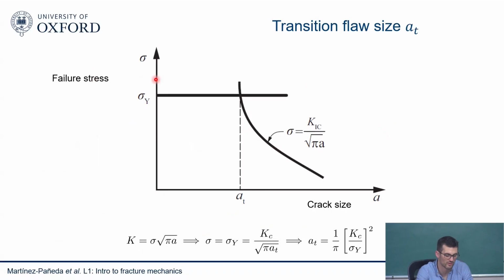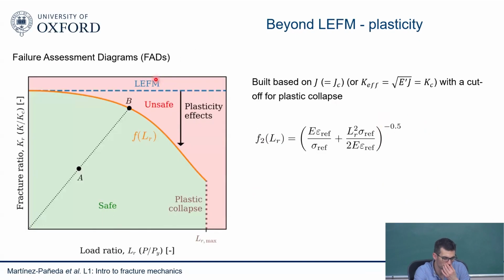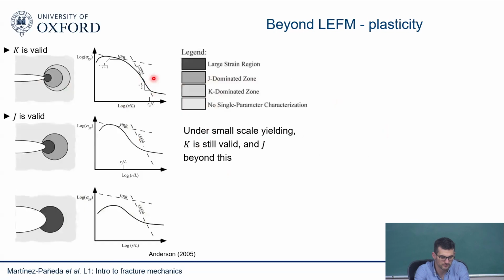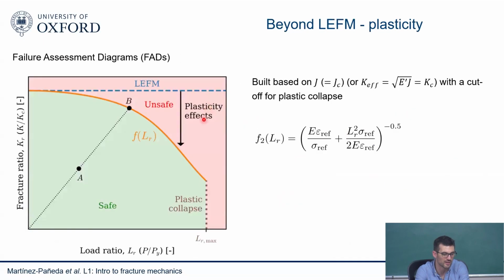This you can also use for elastoplastic fracture mechanics design. But they do something like this, where basically here I'm going to the extremes. I'm taking this stream, the plastic collapse stream, and the linear elastic fracture mechanics stream. But in reality, things will go from here to something like this, more progressively. So this is what a failure assessment diagram captures.